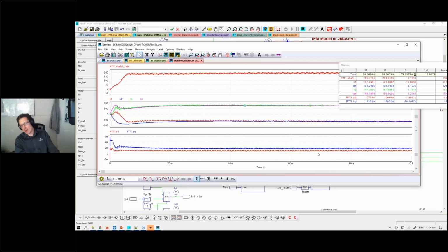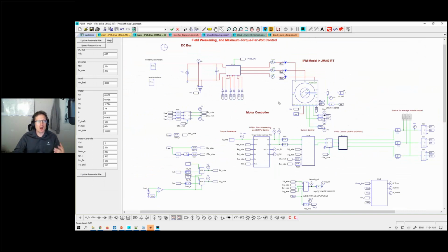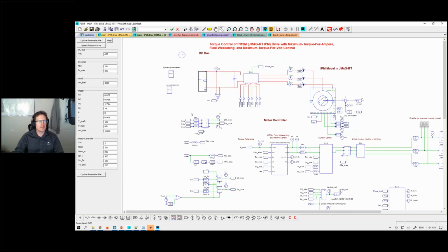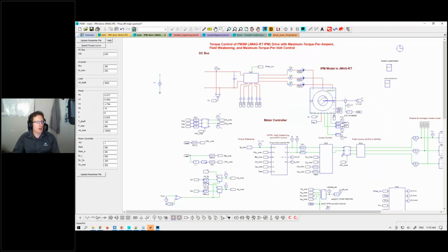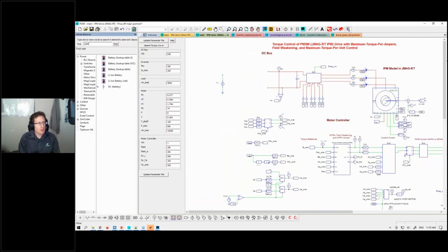And you can include a battery model if you want to as well, of course. Again, this template is now ready for you to edit. So if you wanted to put a battery model here, by all means, put a battery model here. You could do everything from a basic to a more advanced battery model. We've got some lithium-ion battery models in the library here. We could put one of those on.